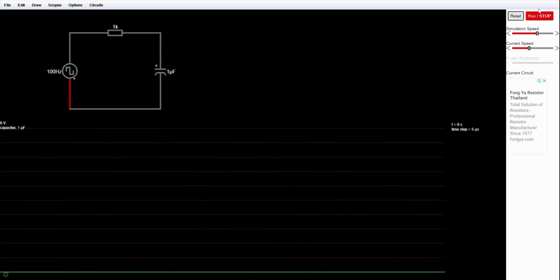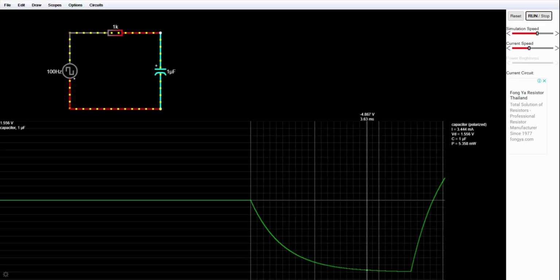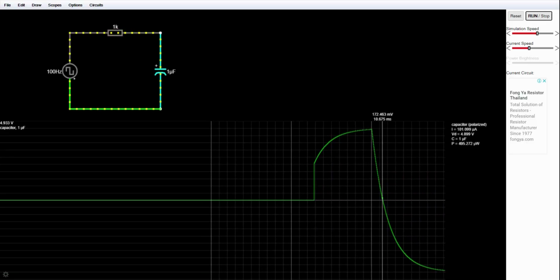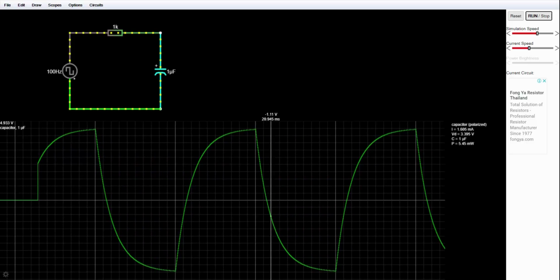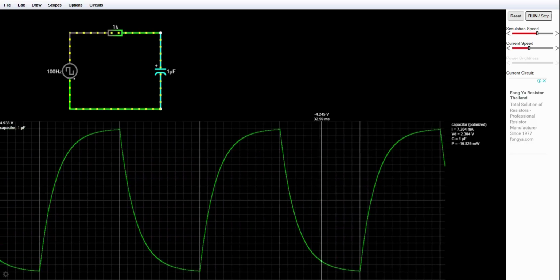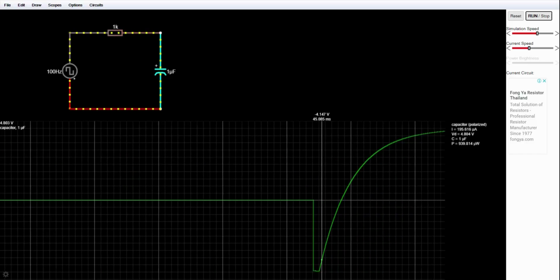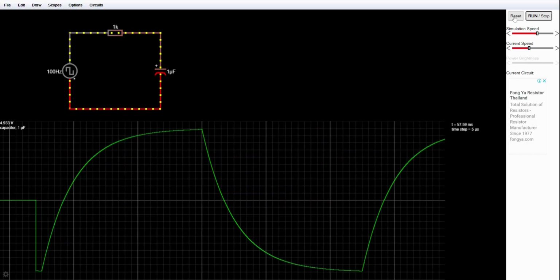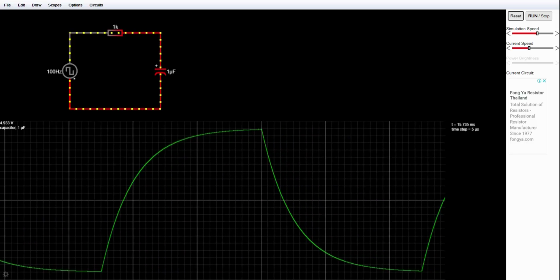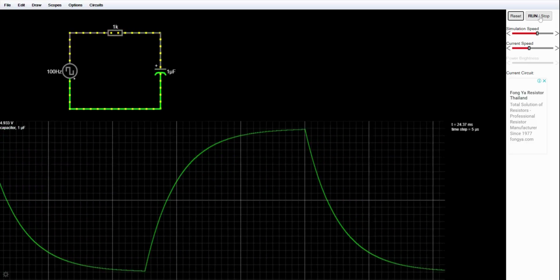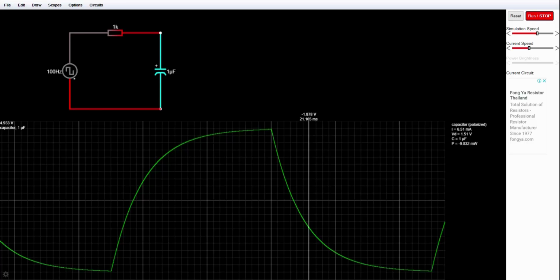Okay, because oftentimes what will happen when you simply zoom in or zoom out, the plot may not automatically update itself, and you may not find a significant change in time. So whenever you are zooming in or zooming out, make sure that you always click reset. So it starts from the beginning at that time scale. And then when you want to take readings, just click stop. It will stop the waveform. You want to continue, then you click this again and it will continue.